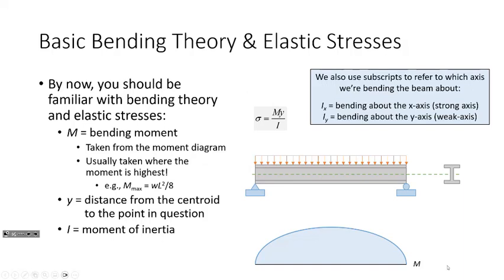But we need the bending moment, the moment of inertia, and then we need the distance y. The distance y being the distance from the centroid, or from the neutral axis, to wherever it is that we're interested in computing bending stresses. So remember, if you're looking at a flexural element along the bending, or along the neutral axis, we experience no bending stress, no bending strain. It is only as we start navigating away from the neutral axis that we start experiencing either compression or tension.